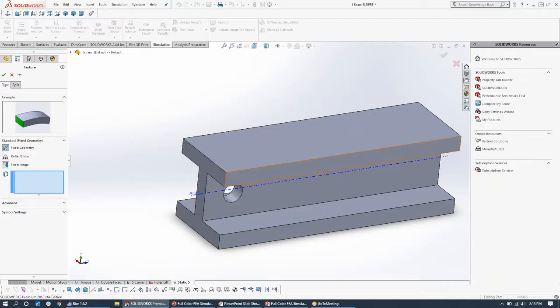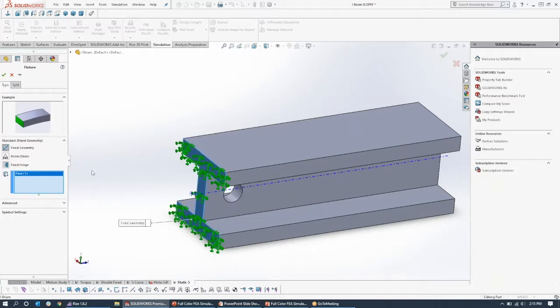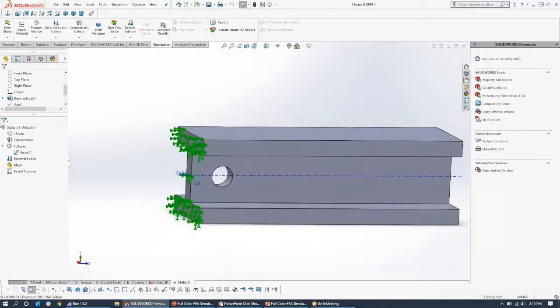And even if I went around and constrained every edge, that would be a very good approximation of what I'm looking for, but it wouldn't quite be precise. So if precision really matters to the data that you produce, then you'll want to pay attention to making sure that you select precisely and only that geometry that you want constrained. So I have constrained that and made it fixed geometry, so I can click OK there. And then let's see.